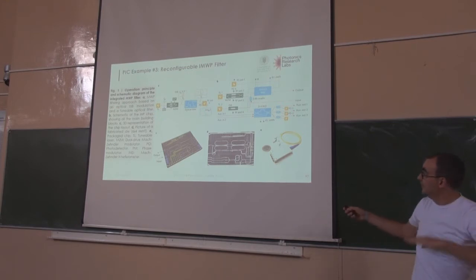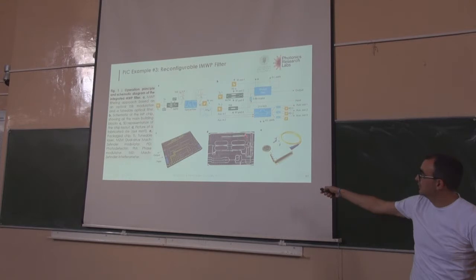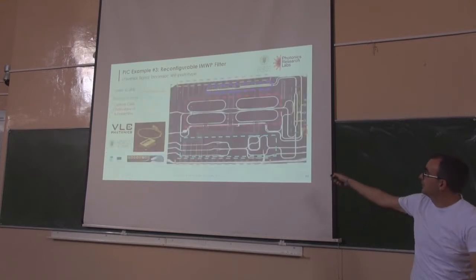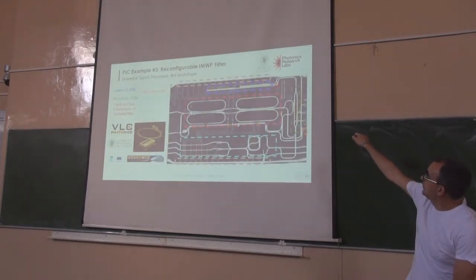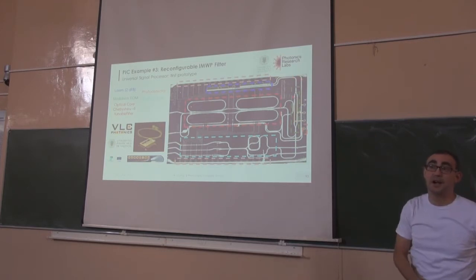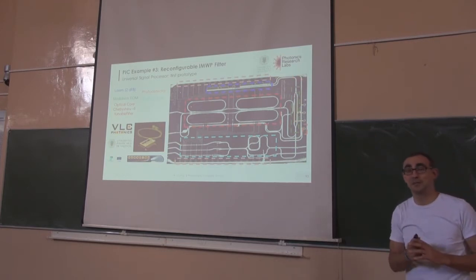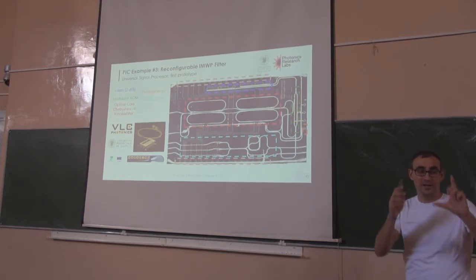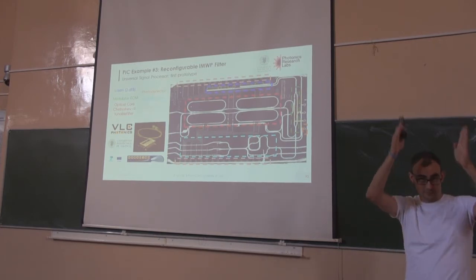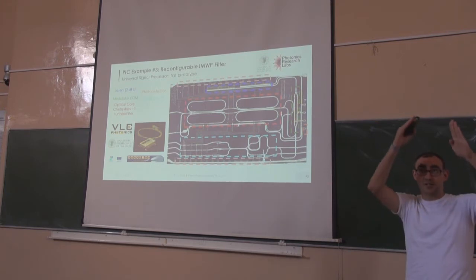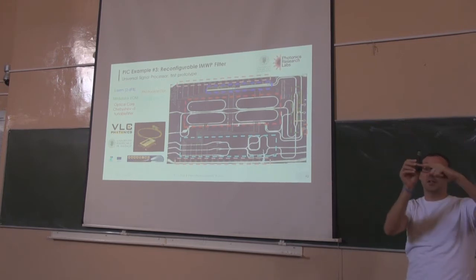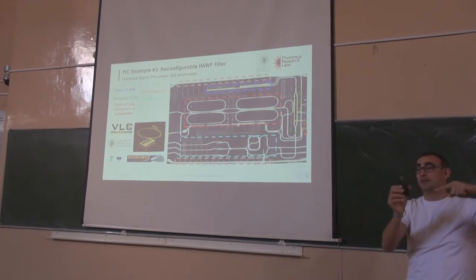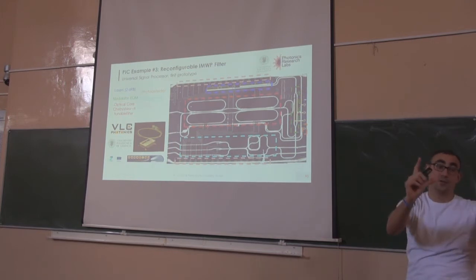Okay, but then this laser, if I can scroll back here better, this laser goes into a bend, a bend, a bend. Bends are very special waveguides, because if you don't do the sidewalls straight and do the sidewalls like this, the polarization axes are tilted with respect to the straight waveguides.